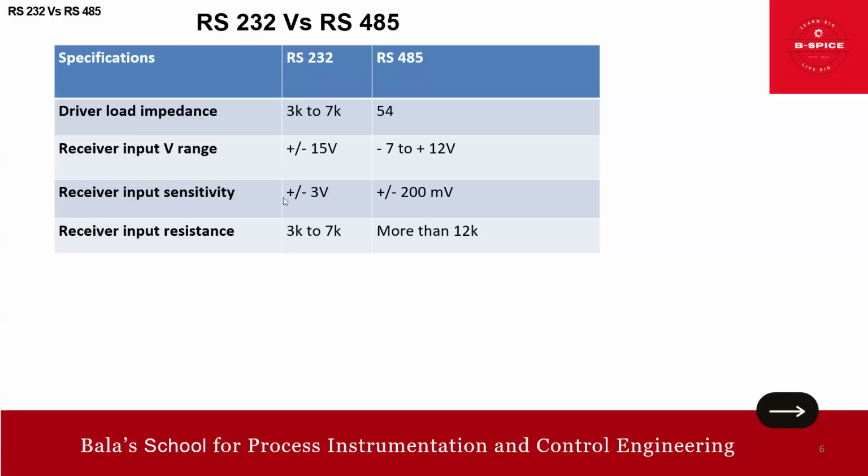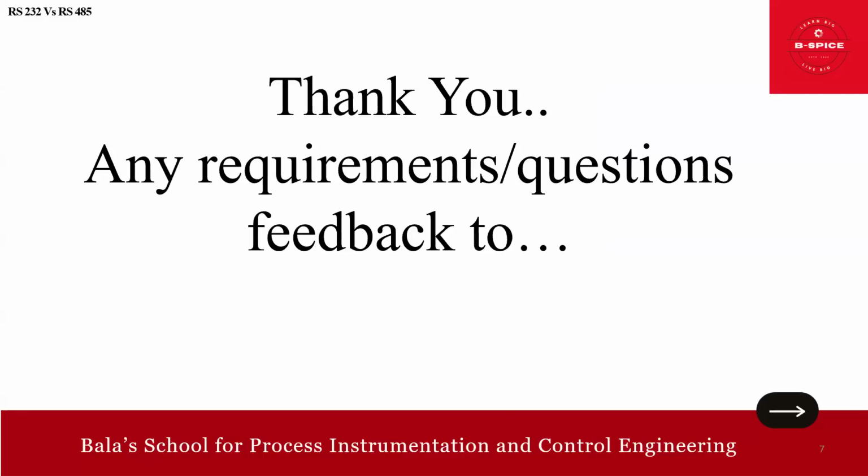Receiver input sensitivity is plus or minus 3 volts, and for 485 it is plus or minus 200 millivolts. Receiver input resistance is 3K to 7K, and this 485 has more than 12K. That's all, friends. I hope you got some insights on RS-485 and 232.